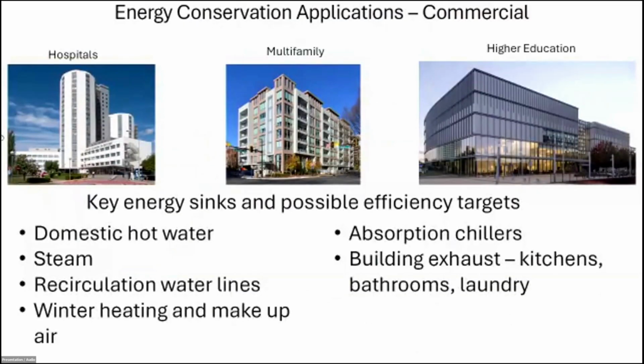So a lot of the projects that I'm working on fall within hospitals, multifamily, higher education, at least in the commercial world. The key energy sinks and efficiency targets that I go after usually fall into the domestic hot water systems, steam, recirc lines. Definitely winter heating air is a big one, especially in my region. I'm in New England. We have very, very cold design days. Definitely makeup water is also another key target.